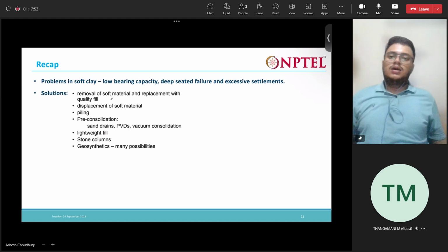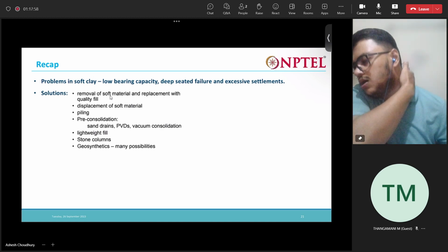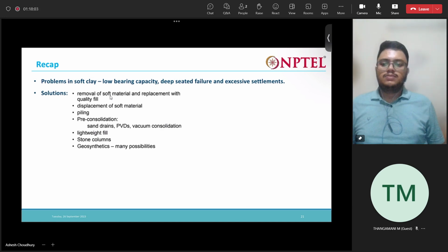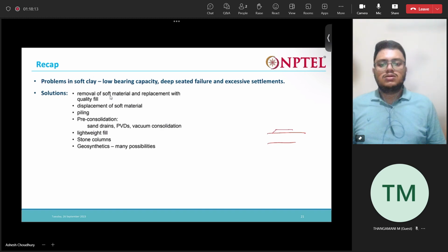All right. So now let us come to the next thing, these problems in soft clay. So what are soft clays? If you have a very soft clay soil and you want to construct something over it, there are high chances that there will be failure. Why failure? Because the soft clay layer has very low bearing capacity, right? So there are chances of deep seated failure and excessive settlements.